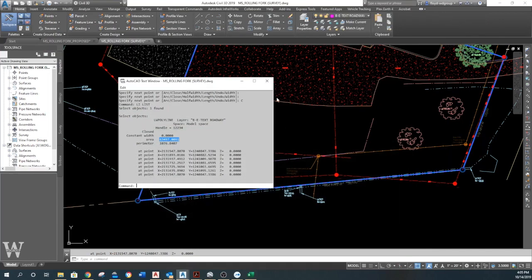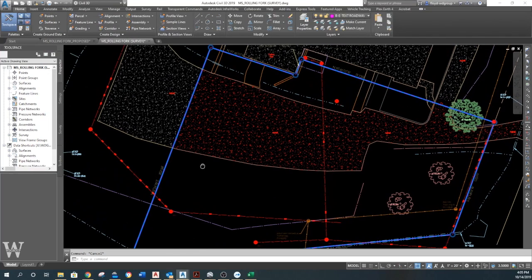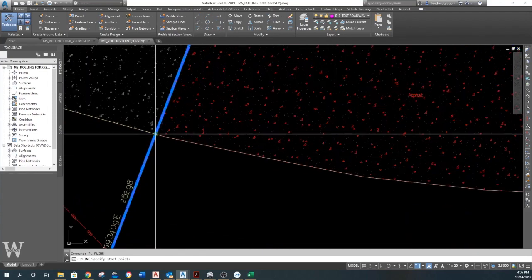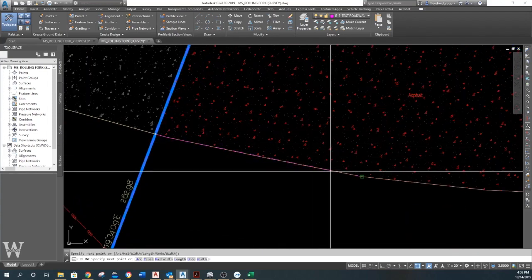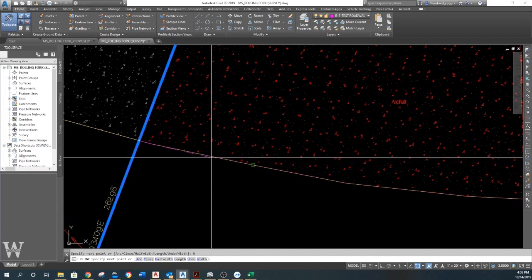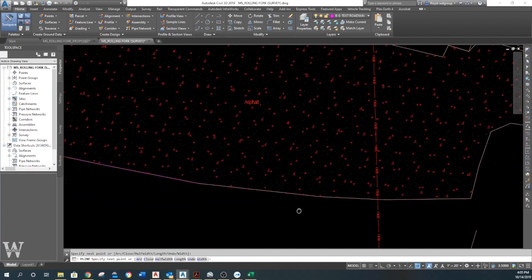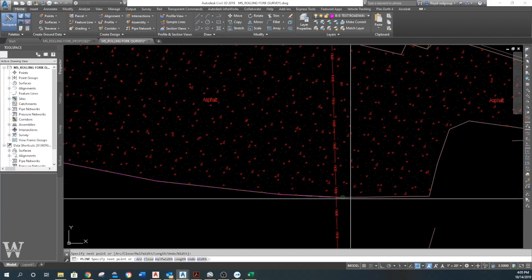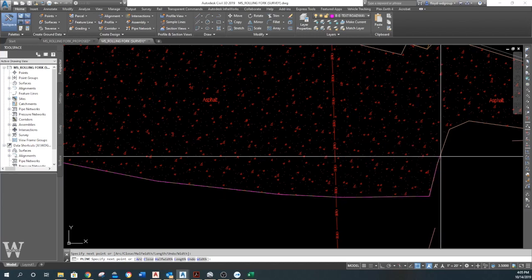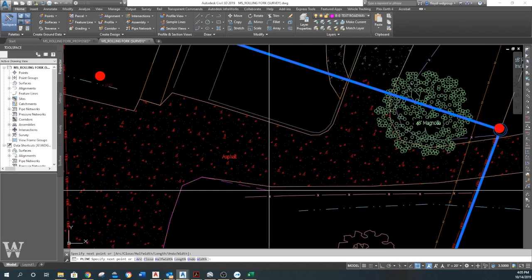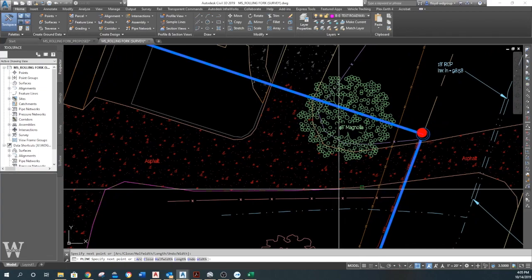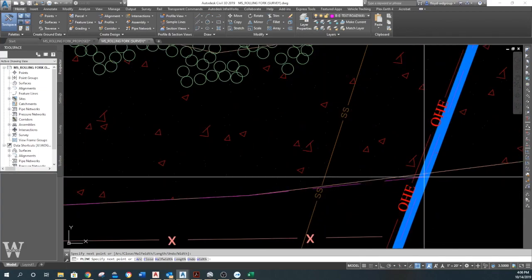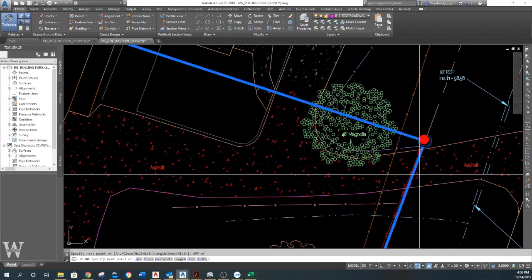Okay, so I'm going to look at my impervious area, and that's impervious is what doesn't shed water. So I'm going to go through my concrete here. I'm just going to go from endpoint, just going to draw a polyline around it, get the area. Now you can do this 100 different ways. I've done it this way all my life.